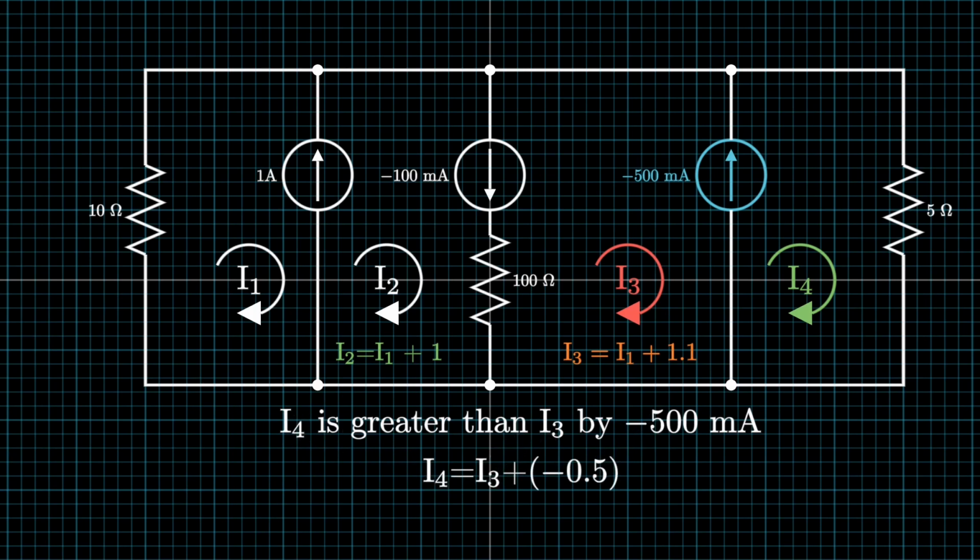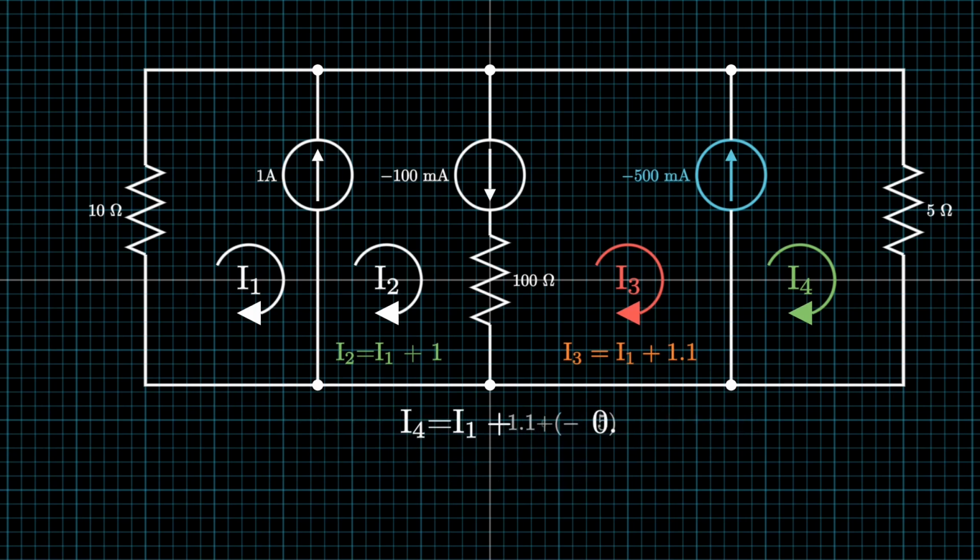We can replace all terms of I3 in this equation with some terms of I1. So let's go ahead and simplify the equation. Simplify, and stash it away again. Now all the currents through every loop all depend on the currents through loop 1. You might be wondering why this was useful, and I'll show you why later, but it'll become very apparent in just a second. Now, I'll show you the supermesh.